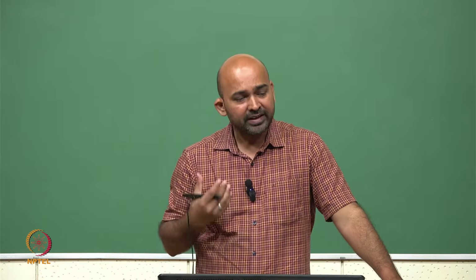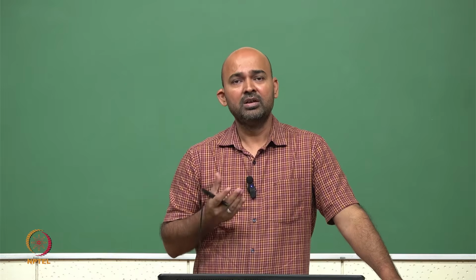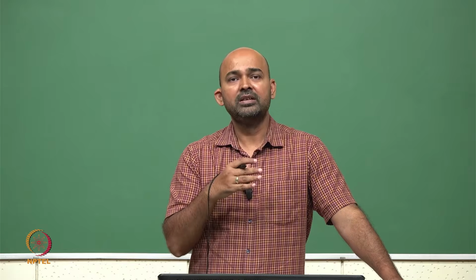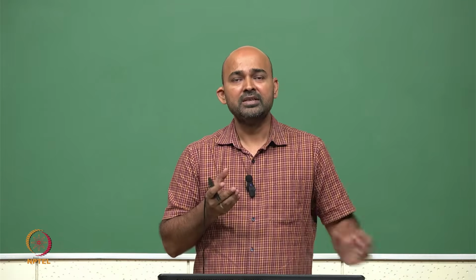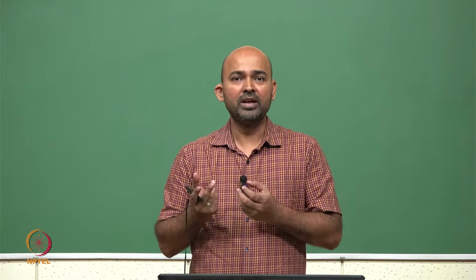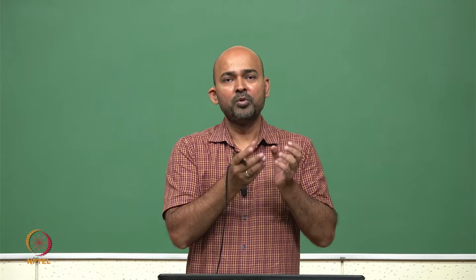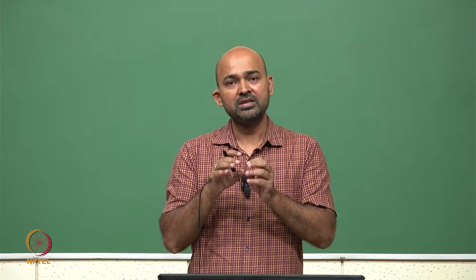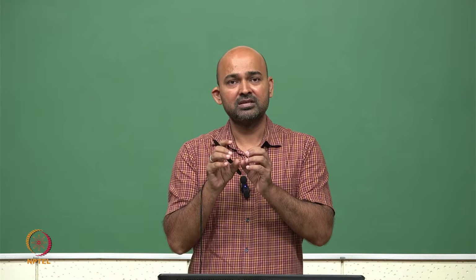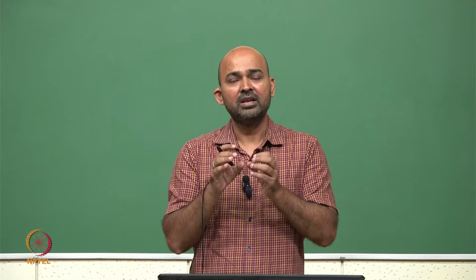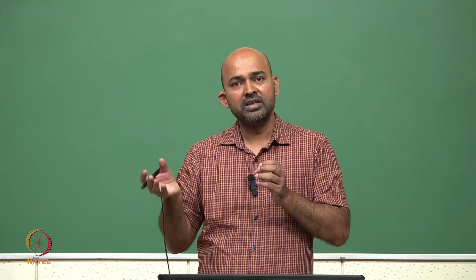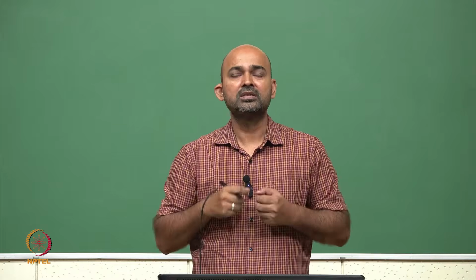So, that was the static characteristics we saw, and we saw there is no static power dissipation. We also saw that the delay of this circuit is dependent on two things. One is the pull-up or pull-down resistance, and the other is the output node capacitance. It acts as a capacitance, which comes from the next stage we are going to connect to this circuit.